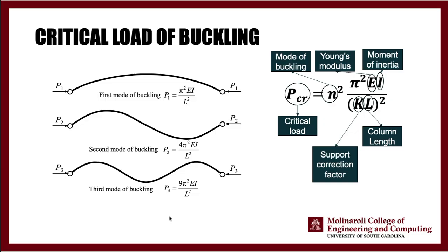But again, we are going to focus on the first mode of buckling. Our critical load is going to be essentially in the first mode of buckling. How do we calculate the critical load? This is the equation we use. Of course, it has a mode factor n for all of our calculations. This mode factor n is 1, so it doesn't really show up in your calculations.